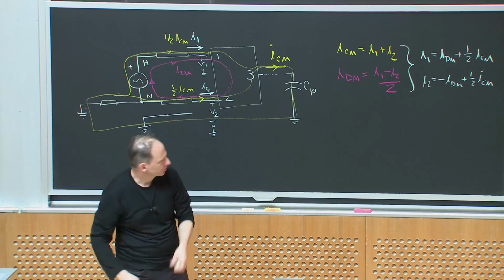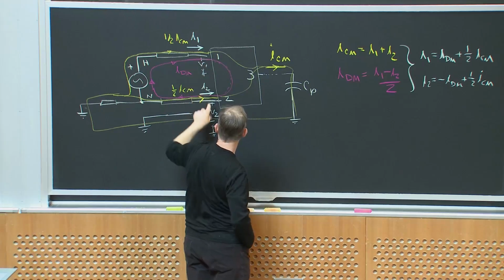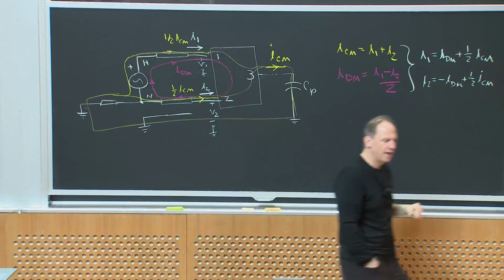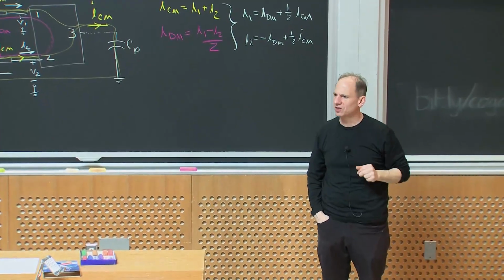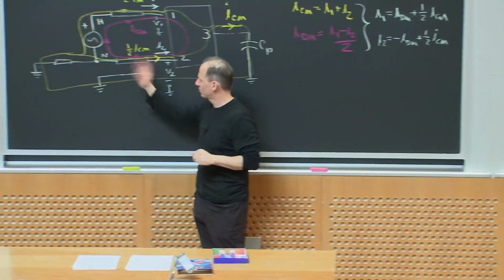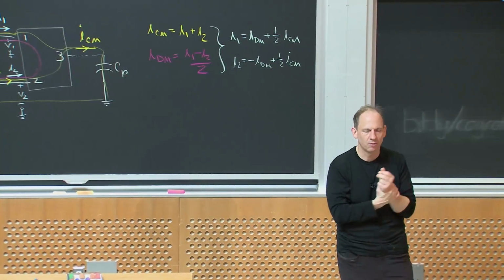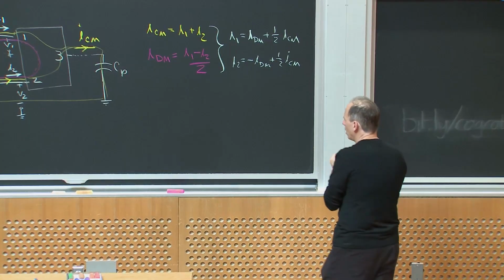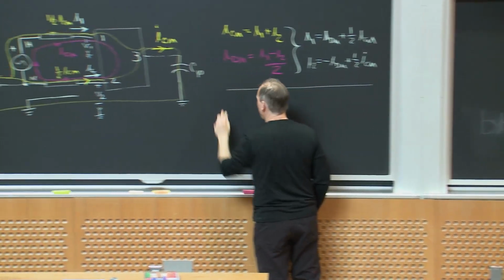What about voltages, right? I've focused on the currents here, but I've said I have a voltage at terminal 1 and a voltage at terminal 2, and I can't assume that the voltage at terminal 2 is ground because of this ground balance kind of stuff going on, and the fact that there's a bunch of cabling here, whether it's switching ground balance or not. There's some difference between that and ground. So we can also come up with definitions of voltage, okay?